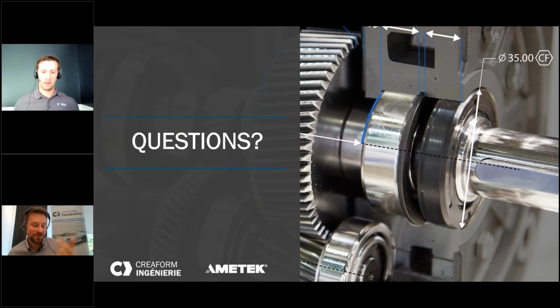It reminds me that earlier in the presentation we said that sometimes you cannot change the tolerance, you cannot change anything. Sometimes you really cannot, but the cost of it being too high means you want to track it by measuring it, because measuring will maybe become less expensive than making something so tight in tolerance that the cost would explode for that specific component.